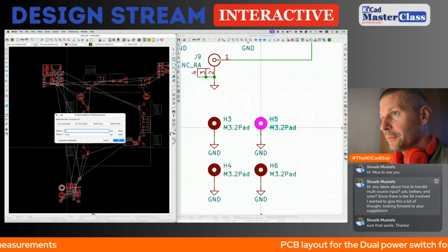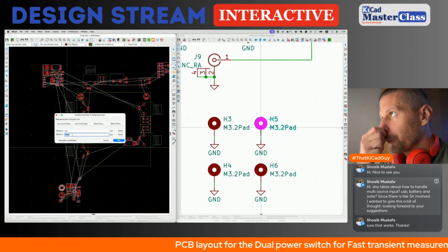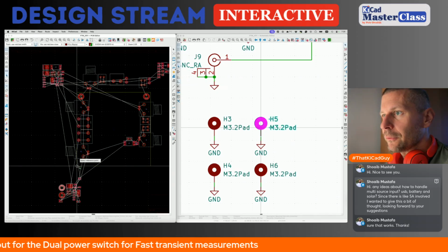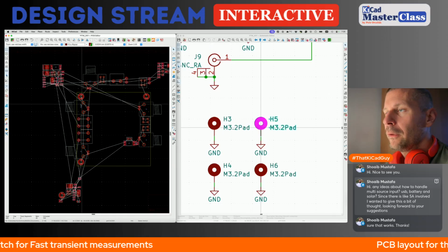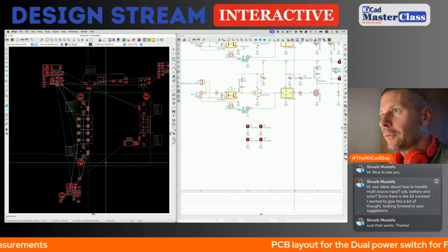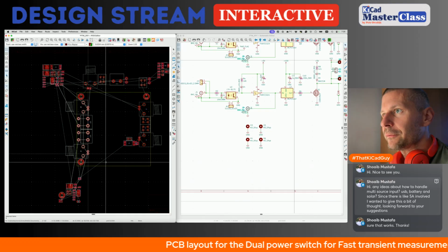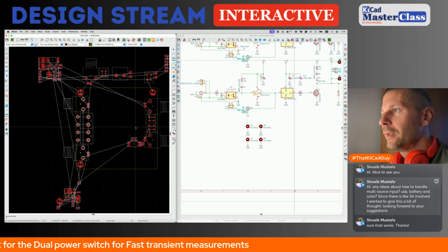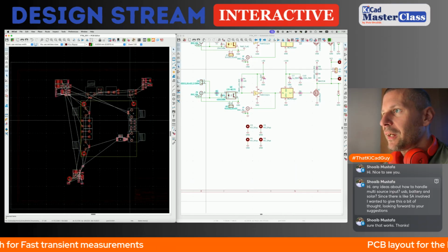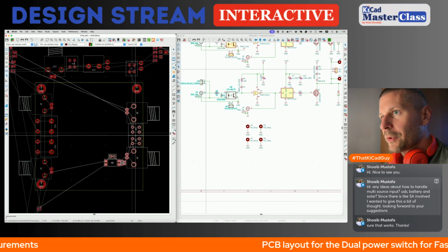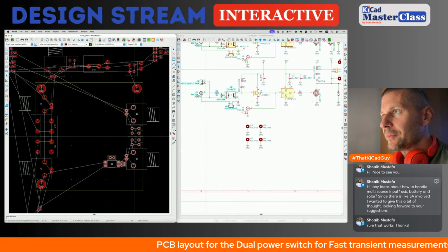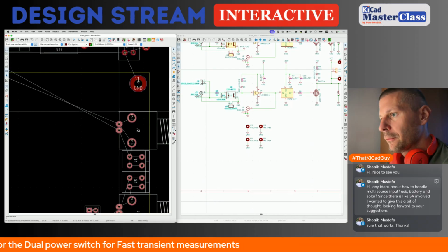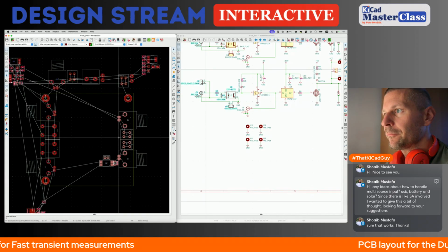I'm going to place the bottom left mounting hole from this corner. Yes, and it means I need these components to be centered, or symmetrically around the center axis of the PCB. So on the other side, it means that these components can go lower, and I canceled the distance now, like this.